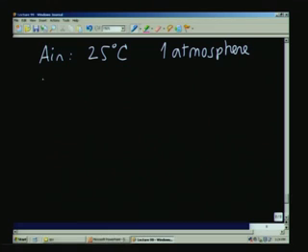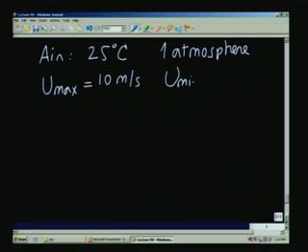So, the delta P is very small compared to the atmospheric pressure. The maximum velocity I know is about 10 meter per second, and the minimum velocity is about 0.5 meter per second. This is the measured value. I am going to measure such values. In fact, I can find out what is the dynamic head.